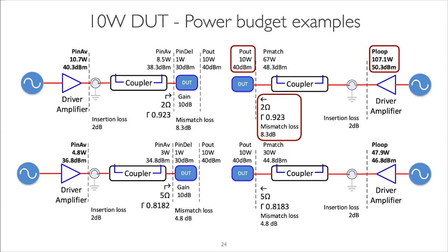Well, now you have a total loss of 10 dB. That's a huge problem, because now, instead of going from a 10-watt device with a loop amplifier of like 10, 20, 30 watts, you're looking at a 100-watt amplifier. So again, even at 2 gigahertz, you could find them. That would be pretty much narrowband, but it's doable. You could find those.